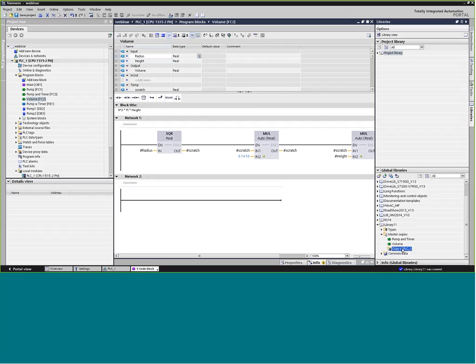Okay, another question I've got here is, is the 1500 faster than the 300? It's funny, because this is a common question about PLCs and how fast they are. One of the reasons that companies come out with new platforms is because, for example, the S7-300's backplane has what's called a K-bus, a communication pathway to go to higher-end modules.